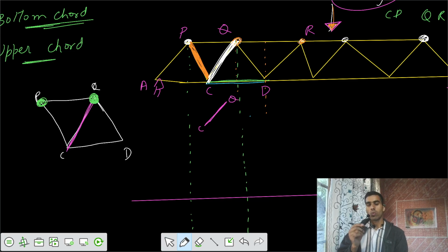So firstly, which of the points starts with respect to A? I would say point C is closer than point Q with respect to A. So you have to keep the point C at the point A location in the ILD. Then you see how is the orientation of C and Q. So that's in this way. So your diagram starting would be in this way. This is your starting of the diagram.